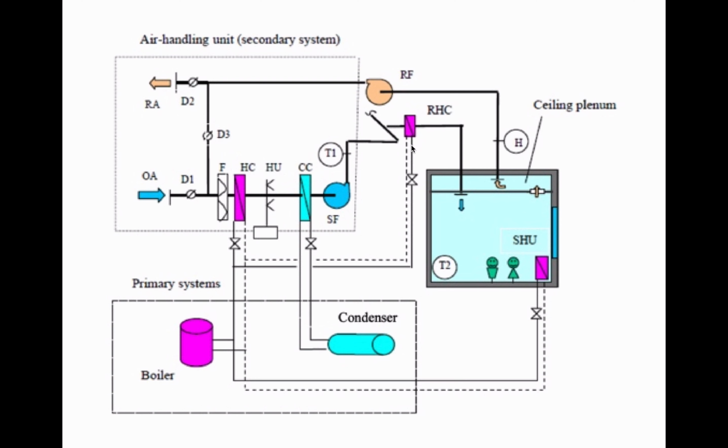Peripheral air terminals will be reheat coils that will provide individual comfort to specific zones, and every space will be equipped with baseboards located along the perimeter walls. All the heating elements, baseboards, reheat coils, and the heating coil will receive hot water from a boiler.